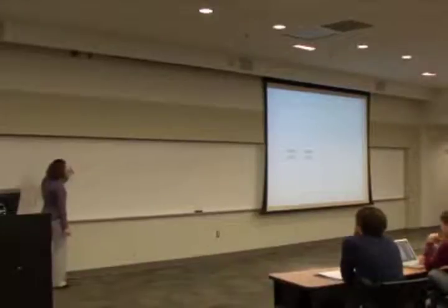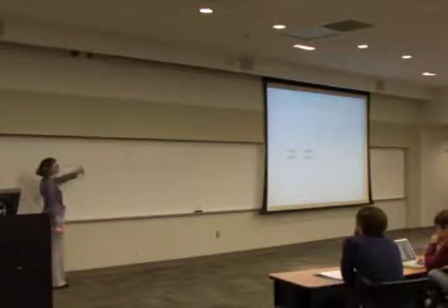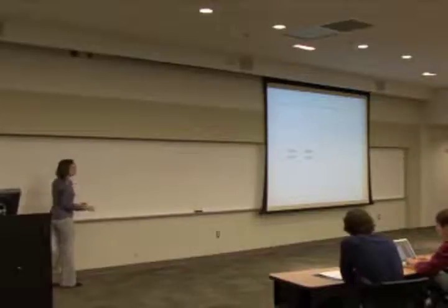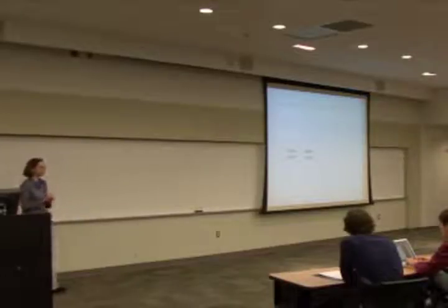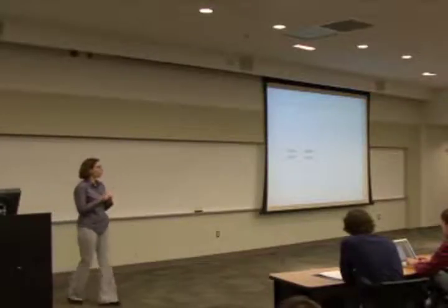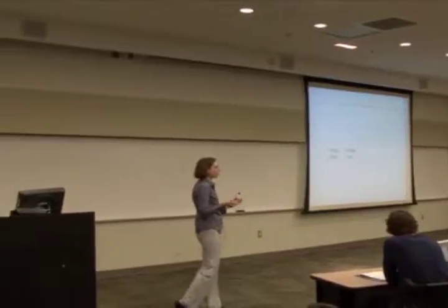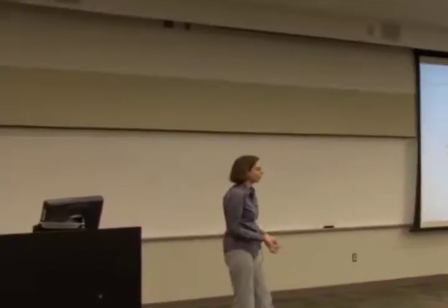Here, if I wait for this thing to settle down to 1, it may take a longer time, so I may have actually shorter time to execute my instructions. So that's why we prefer rising over falling edges, because it's just easier to detect. Because you are not supposed to make an error. If you clock something at the wrong time, you will mess up everything, and that's not a good thing. So anyway, that's about it.